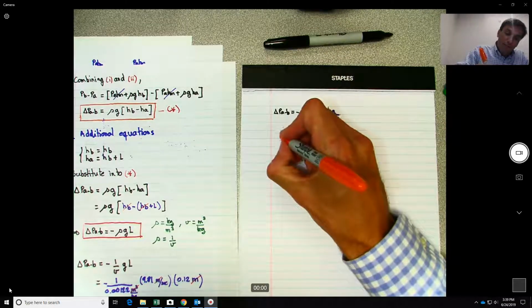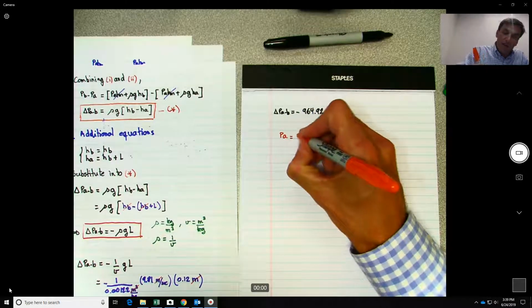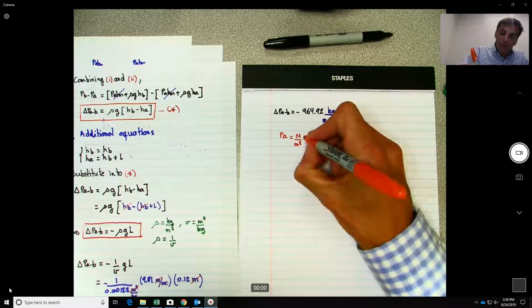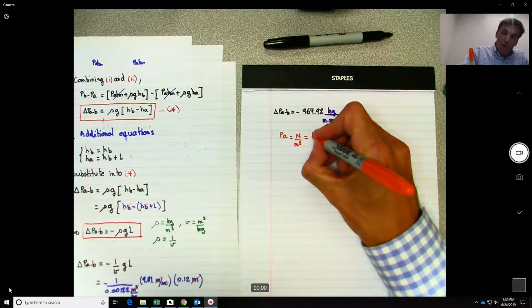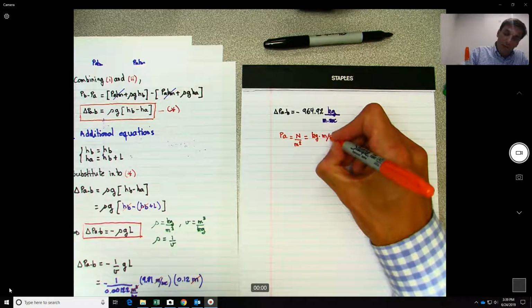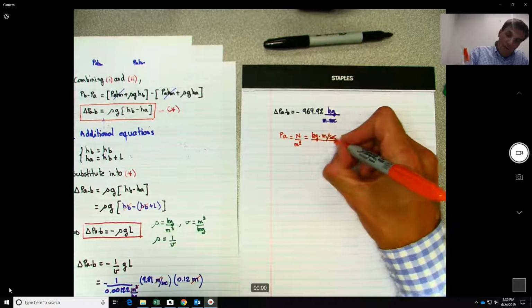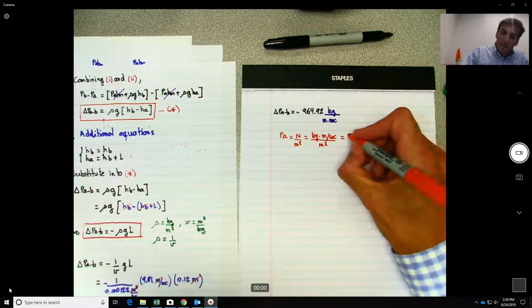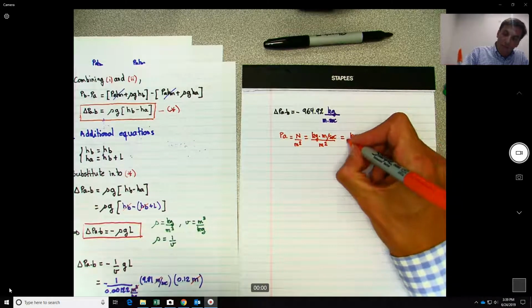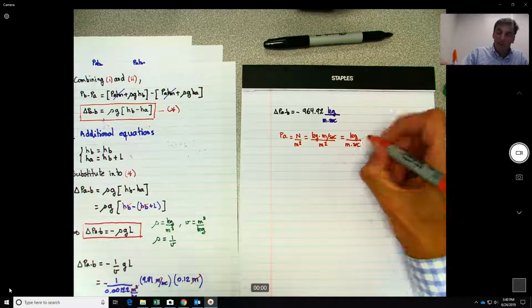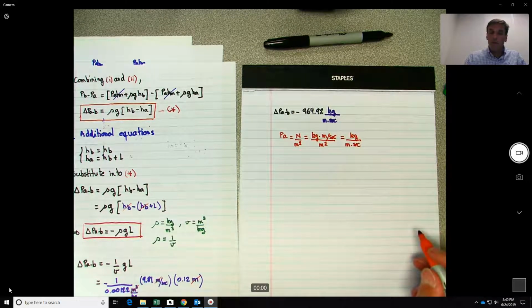So we need to get pascals. So what is a pascal? It is newtons per meter square, and we know that a newton is kilograms meters per second squared. So really 1 pascal is 1 kilogram divided by meter second, which is what we have over there.